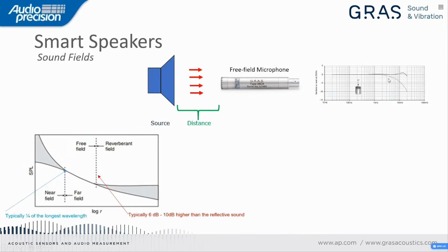So you can see that at higher frequencies, we will measure a lower SPL signal than with a free field signal if we are too close to the source, because the microphone will measure it as a pressure microphone.